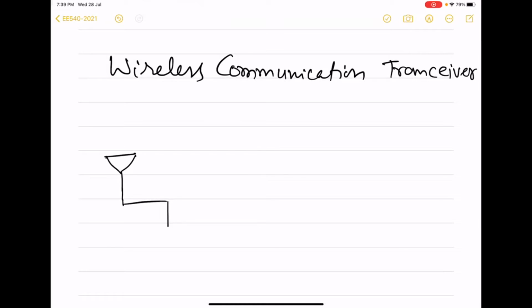So we will have a microphone which will convert voice into electrical signal. That means either voltage or current. And then this can be ideally fed to antenna. But because the strength of this voltage and the current produced is going to be very small, we need circuitry. Not only that, the frequency of these electrical signals is going to be very low, a maximum of 20 kilohertz, so that will lead to large antenna size.